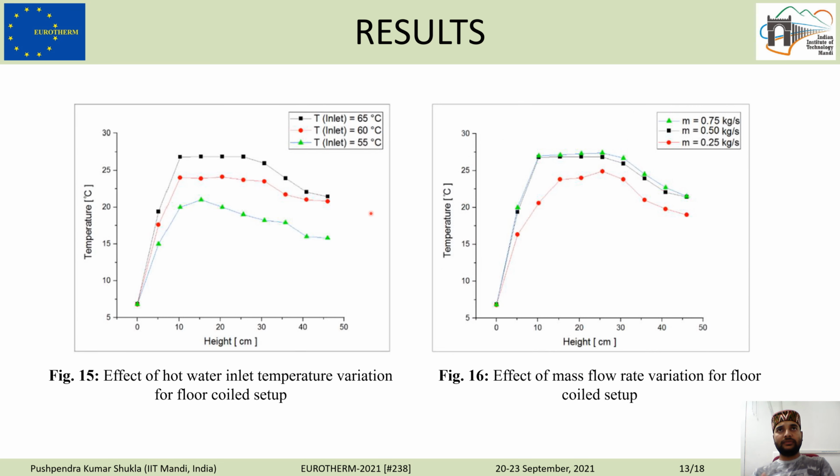For more details or optimizing the design, we had studied the effect of inlet temperature and inlet mass flow rate of the heat transfer fluid. Here we could see that higher temperature, as it is obvious, is giving very good results as compared to lower. But in mass flow rate we could see that if the mass flow rate is beyond a certain limit, the temperature or energy gain after some time is not that significant.